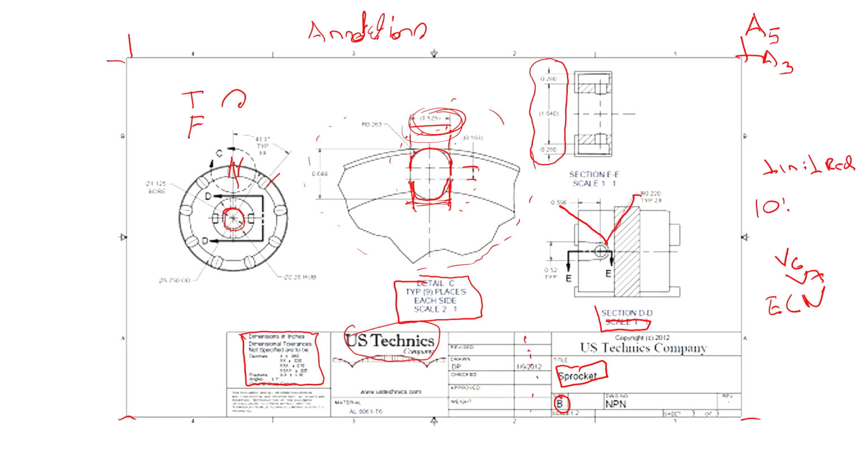Just don't do everything like that. Just a few, the ones that are really crucial and you cannot really have a way to put it through. Like no matter what, this section, you're always going to have to cross the geometry, but never ever cross annotations. This line is a big no. The same way that if you're going to annotate this guy, you're going to bring it out here and then put the number here. Never inside the geometry. And again, never cross the other annotations that you have. All right, so as I said, the drawing has different types of content.